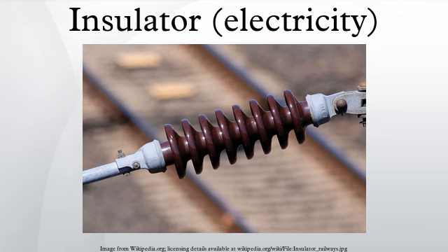Windings that use thicker conductors are often wrapped with supplemental fiberglass insulating tape. Windings may also be impregnated with insulating varnishes to prevent electrical corona and reduce magnetically induced wire vibration. Large power transformer windings are still mostly insulated with paper, wood, varnish, and mineral oil. Although these materials have been used for more than 100 years, they still provide a good balance of economy and adequate performance.